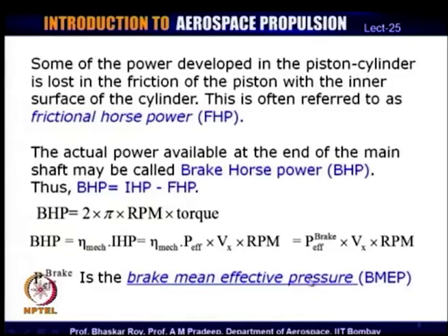Now, this is what we had mentioned earlier as P effective, and now we call this brake mean effective pressure, BMEP. Actually speaking, if you measure this whole thing with reference to IHP, you can come up with something which is indicated mean effective pressure, IMEP. It is possible, but that will be an ideal mean effective pressure. The more useful mean effective pressure is the brake mean effective pressure, which is related to the final BHP